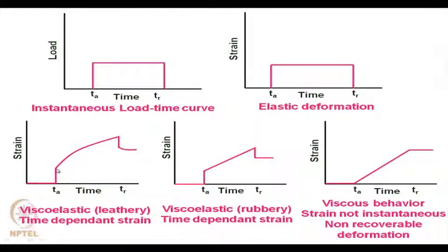This strain was available, then gradually strain increases with time as the load increases, but on release of the stress, this body is supposed to recover its original dimension, that means supposed to come back to this stage, but it is not, though it shows some amount of recovery. Then this is the permanent strain, or permanent deformation, which remains within the body.